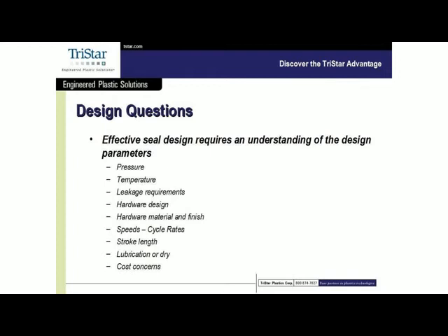What's the temperature range? The minimum, the maximum, and normal operating. What are your leakage requirements? I don't know that yet there's been a seal design that is absolutely dead nuts going to stop all leaks, but I know of PTFE seal design combinations that can seriously reduce to like 1 drop per thousands of strokes. So, what really is your leakage requirement?